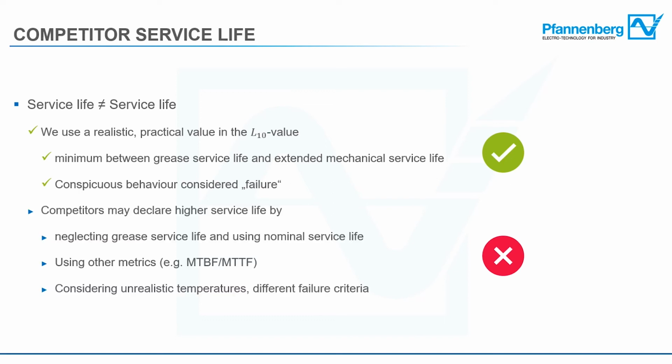Competitors may declare a higher service life, even on the same product, by, for example, neglecting the grease service life entirely, or using just the nominal mechanical service life, or using different metrics entirely, for example, the mean time between failure or the mean time to failure. Remember, at our L10 value, 90% of our products still work. Also, our competitors may consider unrealistic temperatures, for example, fairly low temperatures, or just different failure criteria entirely.